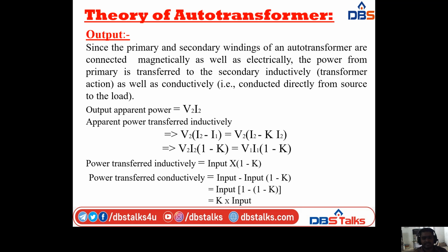The power transferred conductively is input minus input into (1 minus K). Taking input common, that is (1 minus (1 minus K)), which is equal to K into input. So the power transferred conductively is K into input, and the power transferred inductively is input into (1 minus K).